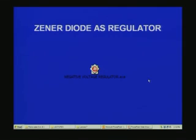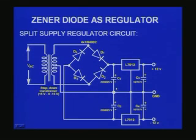Now let me quickly show how we can also go for a dual power supply, a split power supply regulator. Here again you have the same transformer, but you have a center tap transformer, and the center tap is maintained as the common terminal 0, and you have both 7812 and 7912 connected as shown in the picture. The positive is connected to 7812, the negative end is connected to 7912, and the capacitors will have to be carefully connected in the circuit in proper polarity, and then you will get 3 outputs: 0, plus 12 volts and minus 12 volts. All can be obtained by a very simple configuration as shown in the picture.